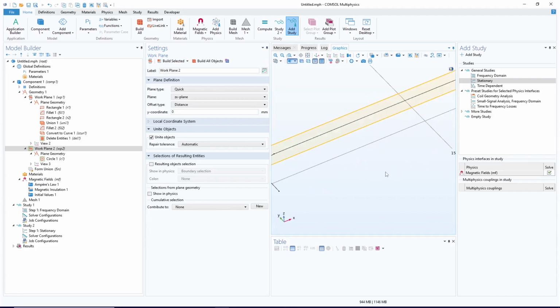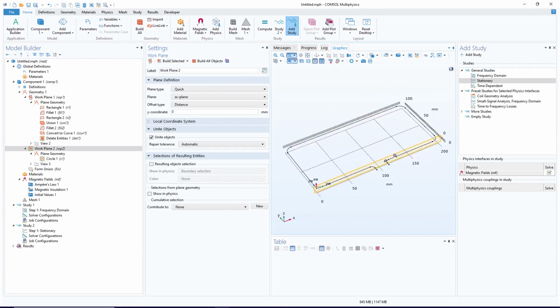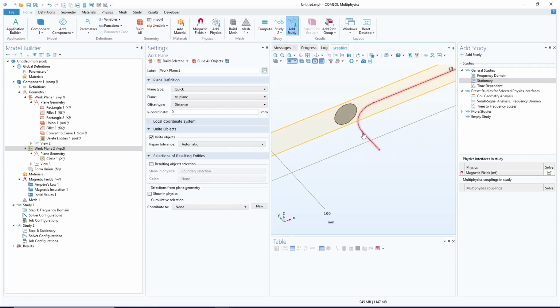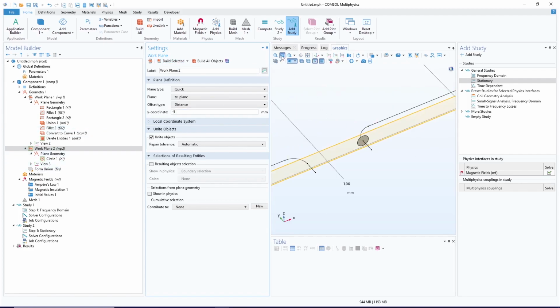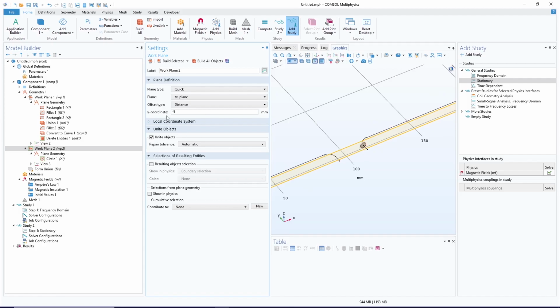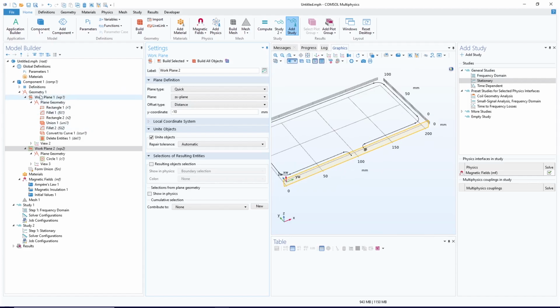Okay, so the circle is there. This plane has to move here. Because I created a fillet of 5, I think this whole plane should be moved 5 units maybe, or minus 5 units. Yeah, okay, so now we have the cross section. Oh no, it should be minus 10. Should start from here. We have the cross section, we have the path, we can sweep this.